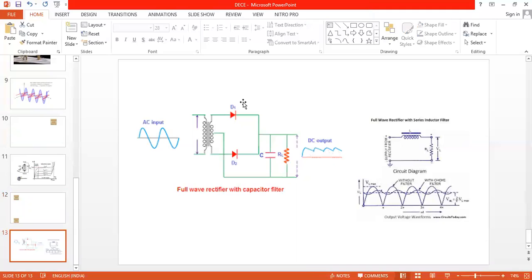In the syllabus also it was mentioned, rectifier with filter. In the examination, if they are asking to explain a full wave rectifier with filter, capacitor filter or inductor filter, always the capacitor has to be connected in parallel. Write the previous explanation you have written for the bridge, the same circuit. This is also midpoint, the same explanation. On your request, if you require midpoint also, I will take it separately.